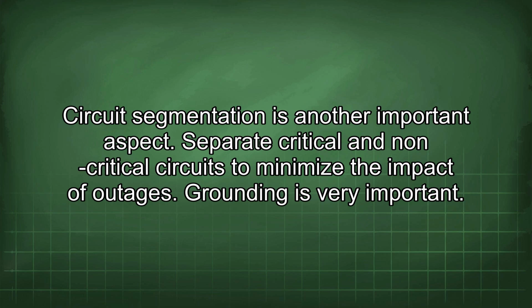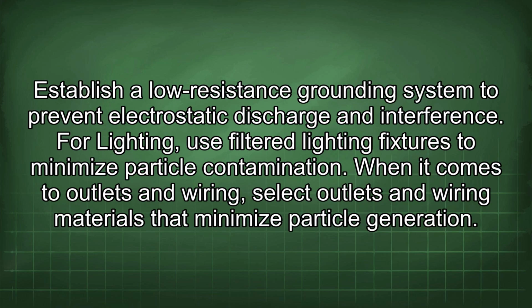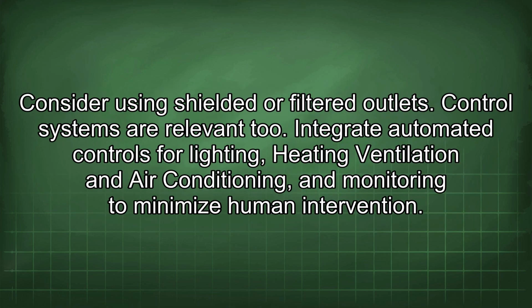Grounding is very important. Establish a low-resistance grounding system to prevent electrostatic discharge and interference. For lighting, use filtered lighting fixtures to minimize particle contamination. When it comes to outlets and wiring, select outlets and wiring materials that minimize particle generation. Consider using shielded or filtered outlets.